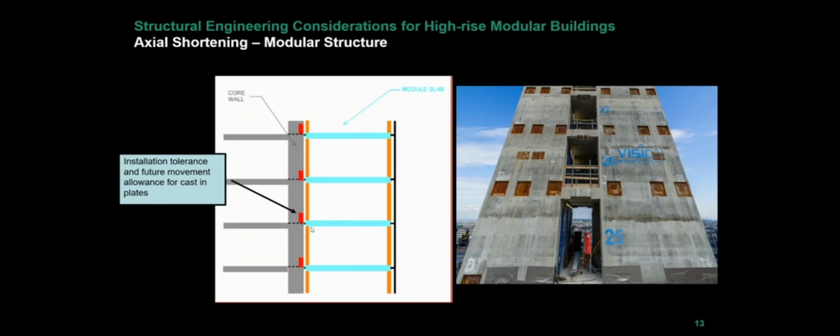Say the connections down at level 10 are installed in the core, which could be 3 or 4 months before the modules are there. So they're going to shrink. They're going to be in a different position on site relative to when the actual module is installed. And that time-stepped analysis needs to be done via the FE models to establish the accurate installation levels of every plate.